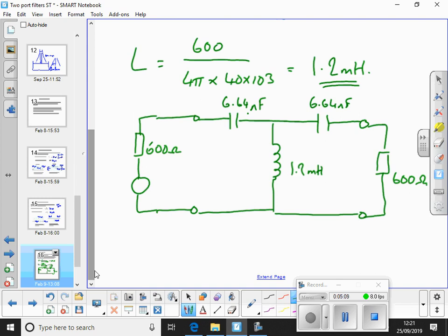All right. Then what you'll do is you'll go ahead and build that circuit and put a variable signal on so you can vary the frequency, and you'll measure input and output across a range of frequencies and make a graph. You can then find out practically where your cutoff frequency is and discuss those results in the light of the components used and the methods used. Yeah.